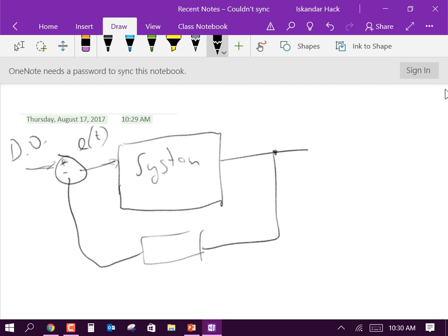And feedback control basically means that we're monitoring the output, we're comparing it to what we want the output to be. So, an example of a feedback control system that's relatively primitive is the AC in my living room at home. Now, these ACs don't have feedback. You either turn them on or off. You set the speed. So the feedback operation there is this young lady here. If the room gets too cold, she walks over and turns off the air con. If the room starts to get too hot, you turn the air con up. So you're the feedback loop in this particular case.